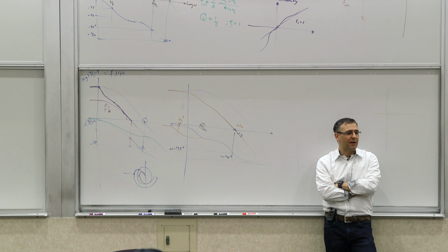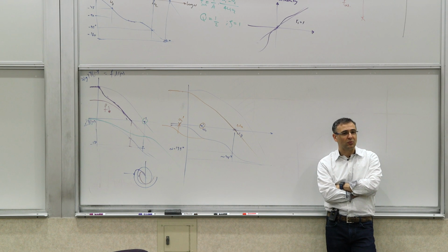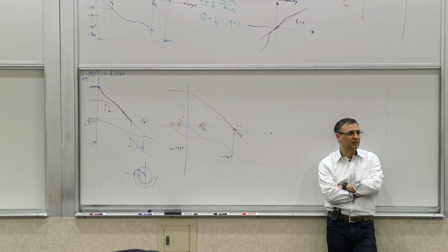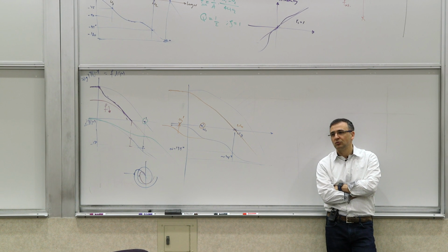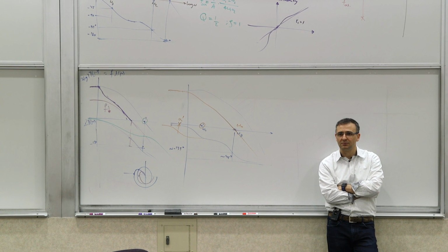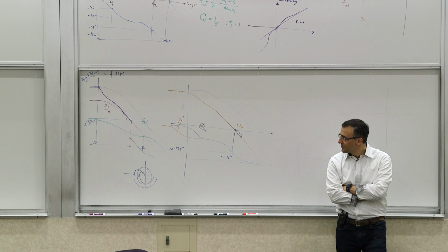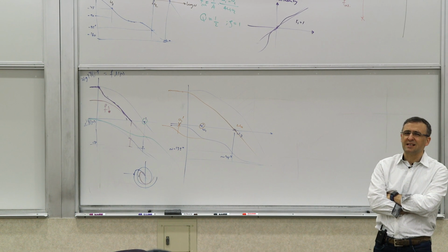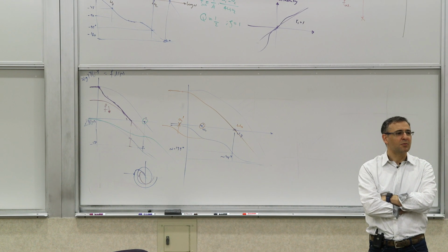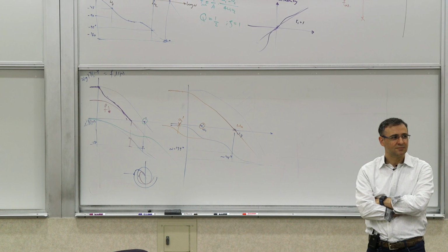and then we got the gain. And later on when we talked about time constants, we saw that the resistance seen by capacitors is what determines the time constants. So if you have a high impedance node, it will have a large time constant, which corresponds to lower frequency response. If they were uncoupled poles, then it would correspond to a lower frequency pole, right? So you remember also we said we try to minimize the number of gain stages for reasons that will become apparent later. Well, later is now.